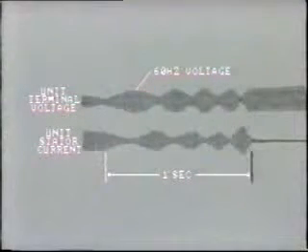At this point, the generator trips offline. You can see that oscillogram recordings such as these are quite valuable to engineers and others concerned with investigating a disturbance. They provide us with documented evidence of the disturbance and allow us to determine if the protection has operated as planned. Let's now move on to our final case study, Case 6, Transformer Energization.